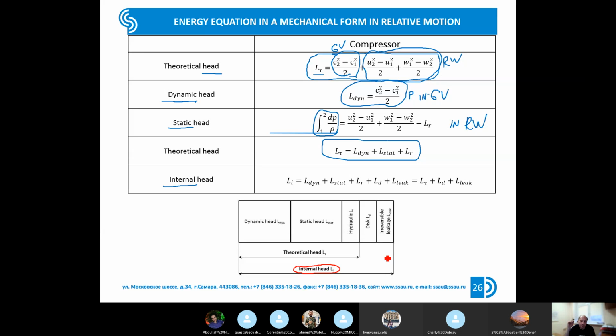Because you have friction on the back sides of the discs, and because you have non-returnable leakages, you lose some of the supplied energy to overcome the resistance of rotation of the turbine disc, and you lose some energy with the leakages.